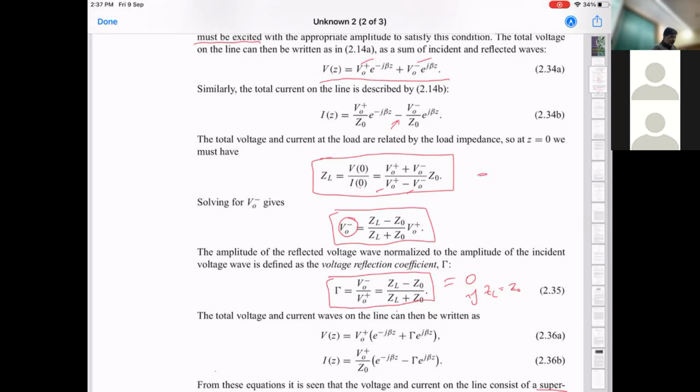So if I have one transmission line here and another transmission line here, just connecting it with some wire like this is going to change that transmission line. So this might be Z0, this might also be Z0, but this part here is not going to be. So that automatically means that you're going to get reflections, and that means that you will not get power going without reflections on either side, which is what you're trying to do if you're trying to make a longer cable.